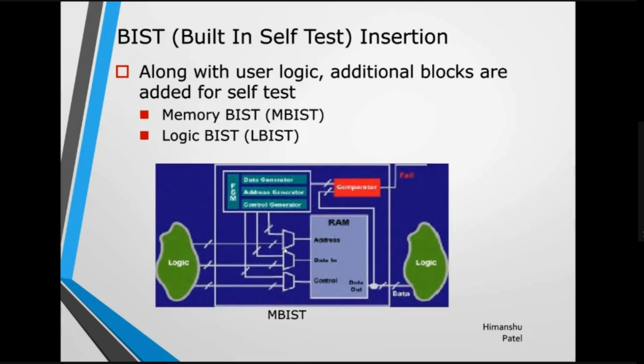So these two are tested in a scan insertion flow as well as a logic BIST flow. When I'm talking here, we're talking about BIST. You can automate this scan insertion flow by logic BIST with the same BIST mechanism. How you use it for testing memories, you use it to test the logic also.